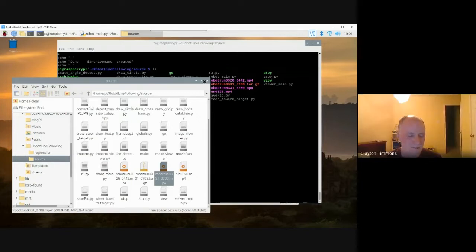Yes, someone else had mentioned that to me, and I thought of that also. I haven't tried that yet. I did use the RAM disk. I switched to a Raspberry Pi 4, which has even more memory, but the RAM disk is extremely fast, so that's working. Although saving as a JPEG, I'm pretty sure I could go back to the SD card now. I haven't tried that, but I'm pretty sure that would work as well. In theory, it should work because a camcorder uses those SD cards.